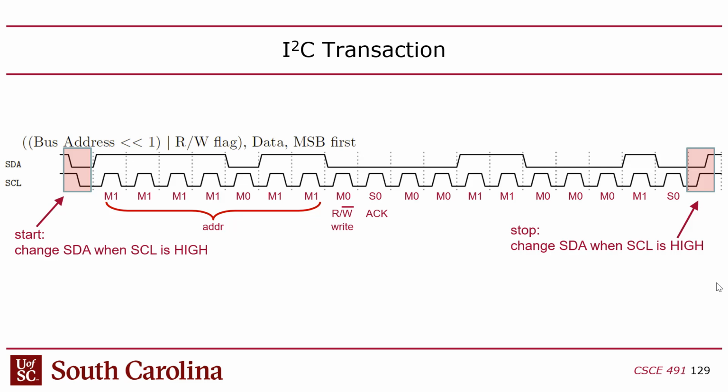All right, so it's a little easier to read, though, because you don't have to look for edges. You just look, whenever the clock is high, that's when you look at the corresponding value of data. That's how you can decode these.